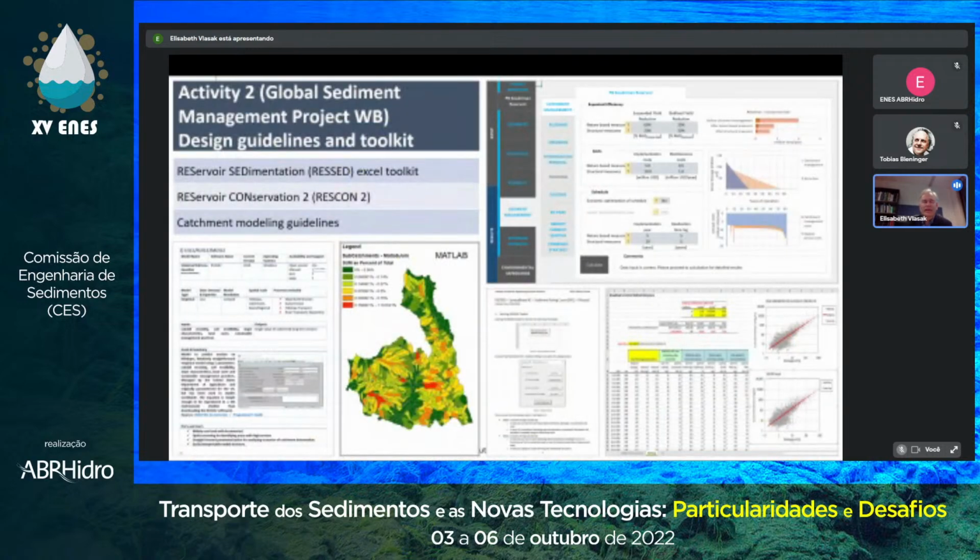Now, to help you a little bit, we did a World Bank project together with Pravin Kaki. We also had a seminar in Brasilia together, I think. Some of you might have been there. In the meanwhile, the project is finished already this year. We have products which you can download soon, in a few weeks hopefully, which is this one here, ResConDo. It is not a numerical model, but a way to estimate, in a very simple way, a first idea: if I do sluicing, tracking, hydrosuction, dredging, or flushing, what is the cost and how is the efficiency?